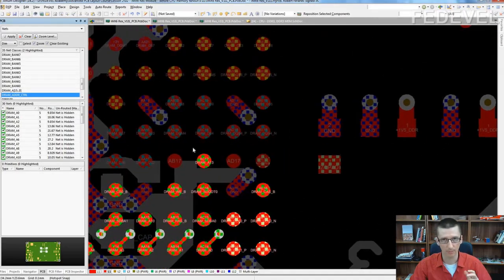We will use through-hole vias for these paths, and we will start with differential pair because differential pairs need to be routed together. And on the beginning, you can actually decide how you are going to route them. If you first route these, you may not have space to route the differential signals properly.